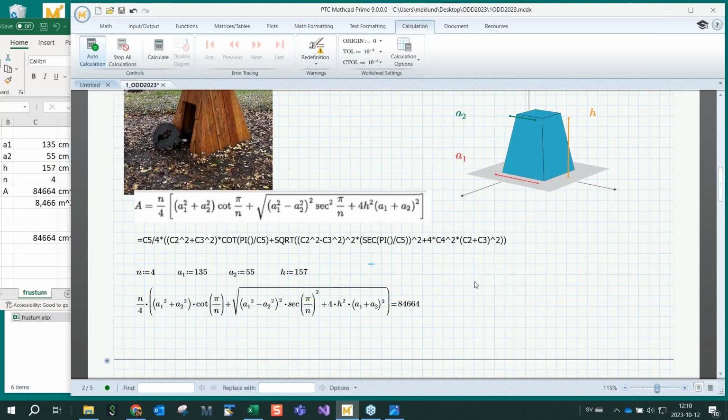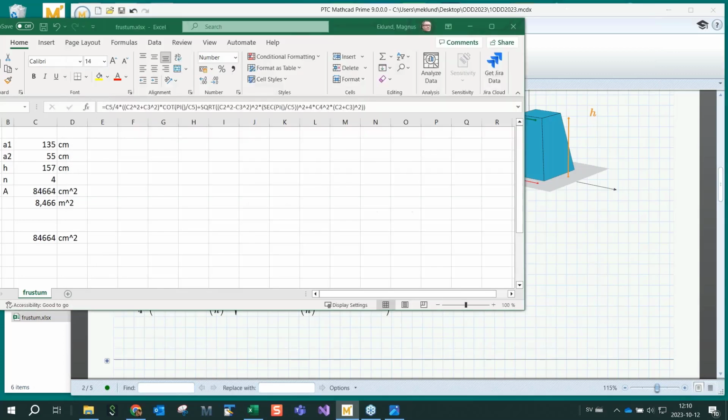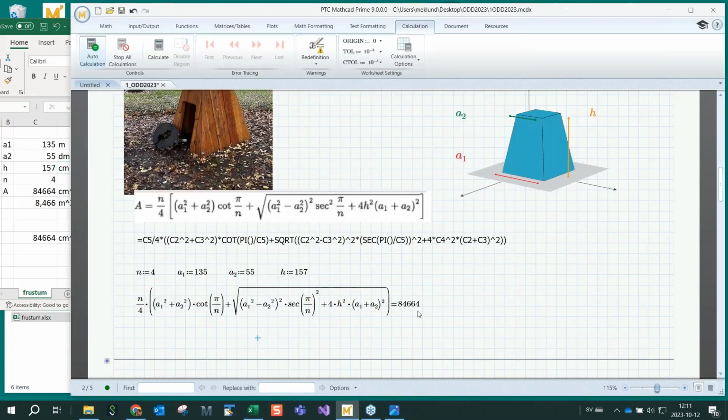But we can do more than that in Mathcad. One other really nice feature in Mathcad is that we can use units on all our values. Basically, we can't do that in spreadsheets. If I change something here saying this is in meters, meter, and whatever, decimeter, nothing will change. It would require complicated programming in spreadsheets to figure out units and things like that.